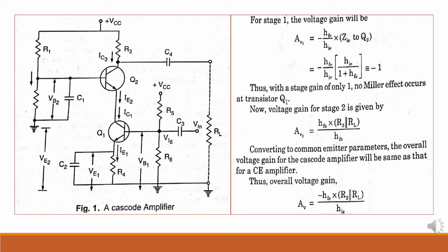Now here in this figure, how to obtain the gain we can find out in this way, from the DC conditions of the circuit. It may be observed that the emitter current of the transistor Q1 is set by VE1. As we can see from the figure, VE1 is nothing but the voltage appearing across C2 and R4, in the left hand figure.